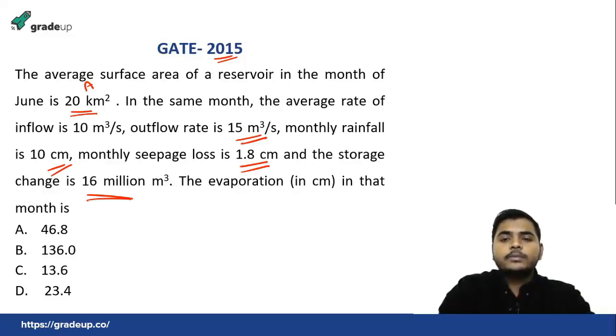So firstly, precipitation plus the volume or depth which is incoming, surface inflow, VIS, plus anything more is not here, groundwater flow is not here, so directly it will be equal to the outflow, that is VOS, plus seepage loss, plus storage change delta S. Now this delta S we can assume anything, as we do not know at present whether it is positive or negative.